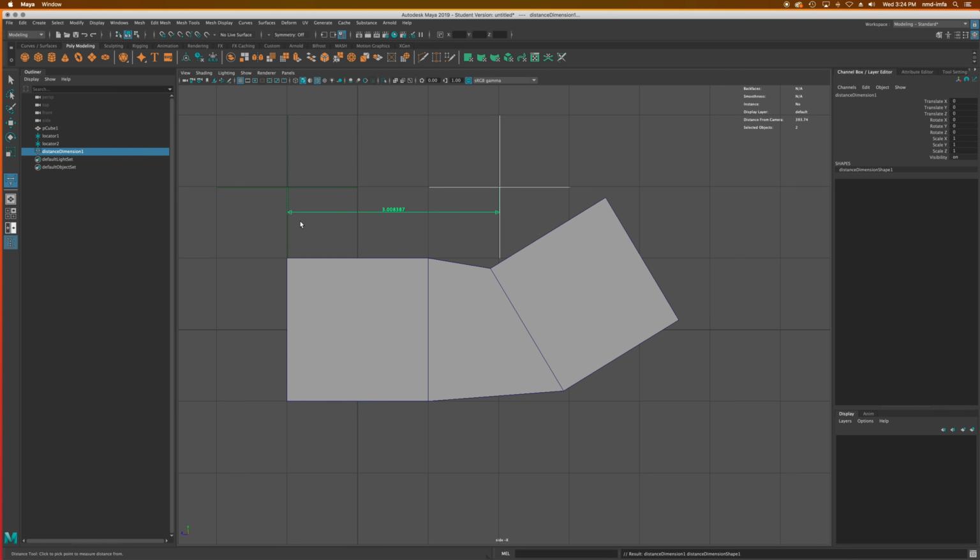You'll notice that was 3 units plus 0.008387 because it wasn't exact. I kind of went 1 unit over. Now, if you hold down the letter V while you place these, it'll snap to vector points on your object. That is a very useful thing to know. So I click there, and I click on this one here, and you can see I got a perfect measurement of 2. That is 2 Maya units, 2 inches, since that is my unit of measure.